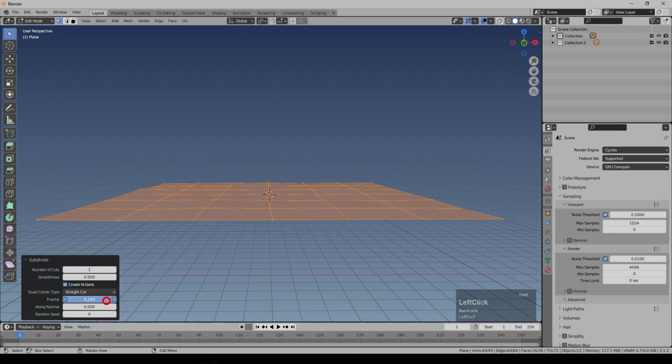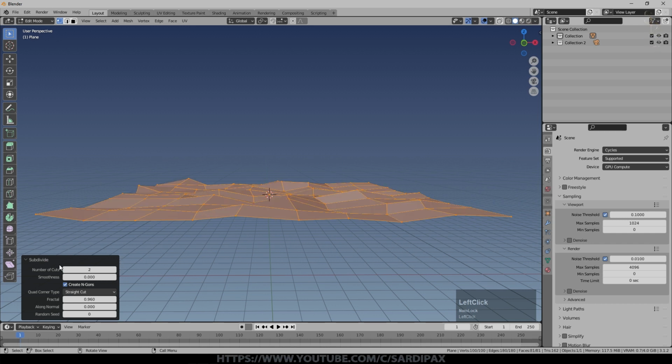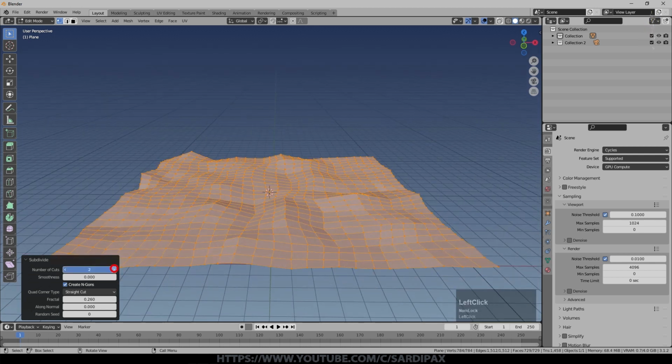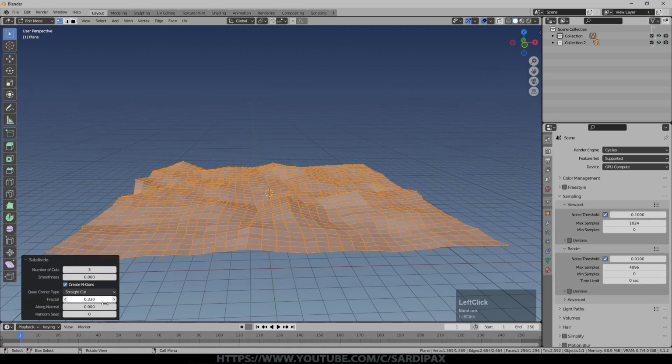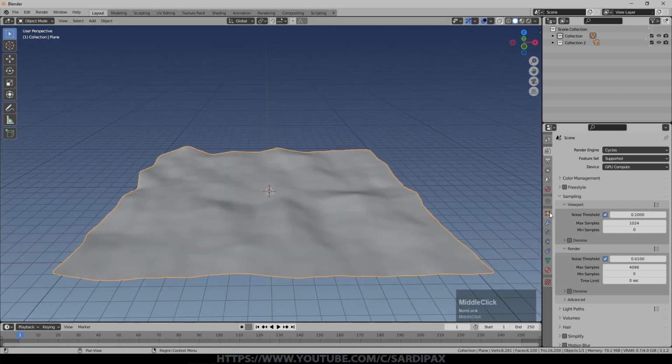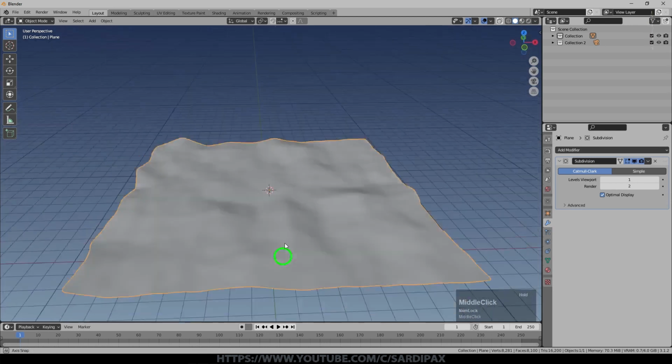But then I'm going to start to increase fractal, which will start to give me some variation in the surface. And I'll increase that a little bit. Right click, subdivide again, and I'm sort of getting small bumps now. I do want a fair bit of geometry, because the geometry nodes will use this in order to determine where to instance my particles, and I need to be able to have sufficient geometry in order to be able to define that. So I'm just going to put that up again, perhaps we'll increase that slightly, one more, and then we'll come out of edit mode, Control 1 for the moment, and we'll set it to shade smooth. So Control 1 has just added a subdivision surface on there to increase the geometry further.